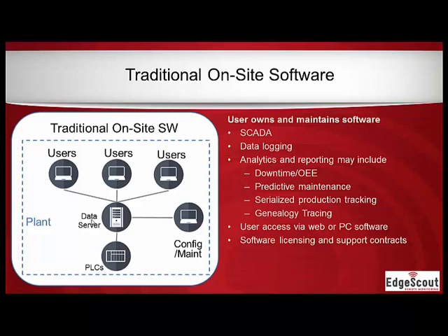And what I mean by analytics are things like downtime analysis, overall equipment effectiveness, predictive and preventive maintenance programs, serialized production tracking so that you know specifics about a particular customer order as it went through your system, genealogy tracing so that you know what raw material went into which end products that came out of your factory so that you could do a targeted recall if there was ever an issue with a batch of raw material.